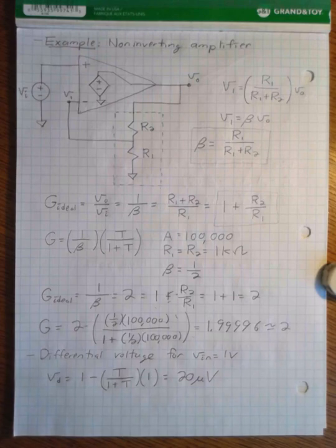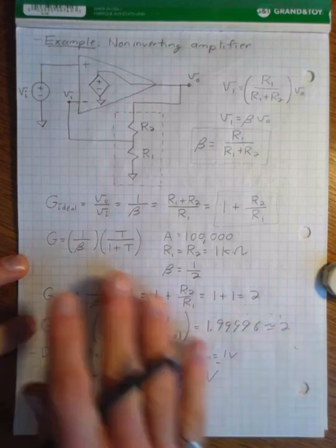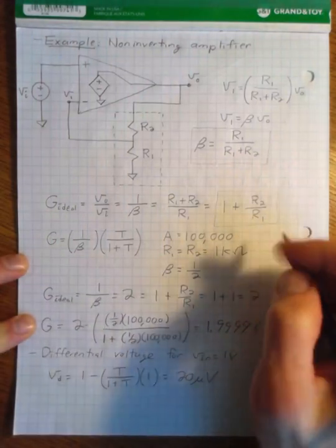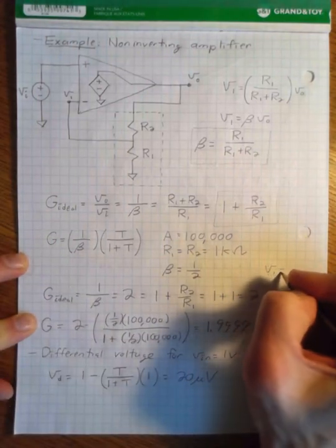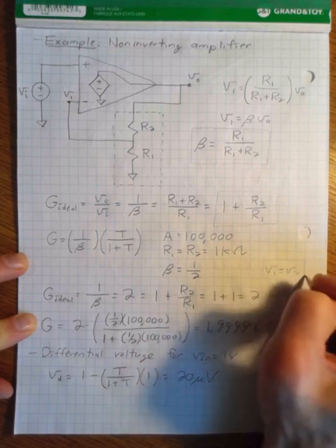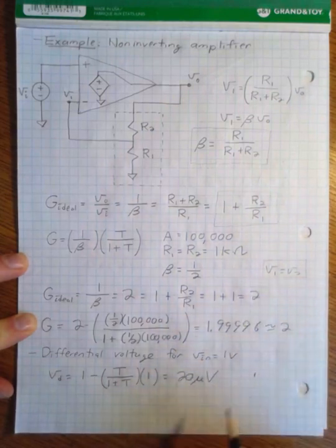There are lots of electrical engineering circuits, particularly communication receivers and low noise instrumentation type circuits, that can measure voltages that are much smaller than 20 microvolts. And so it's approximately 0. Obviously things hold together. The analysis that we perform for the V1 equals V2 assumption gives us the proper gain.